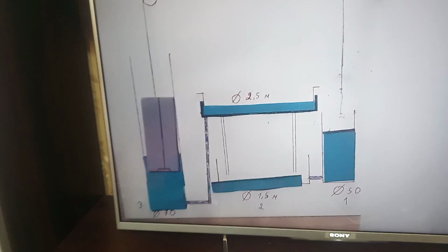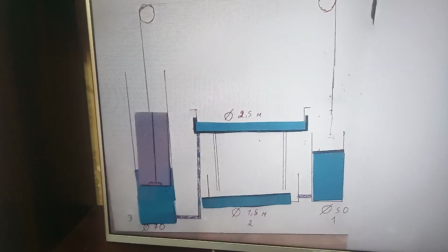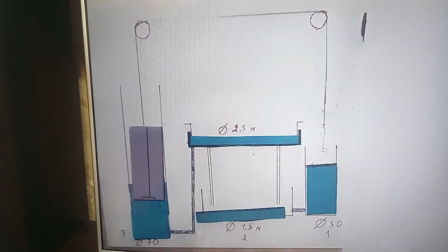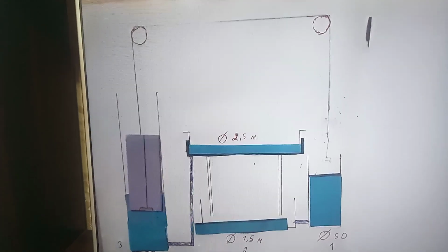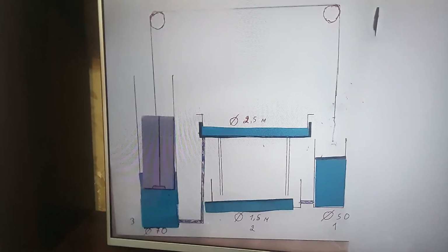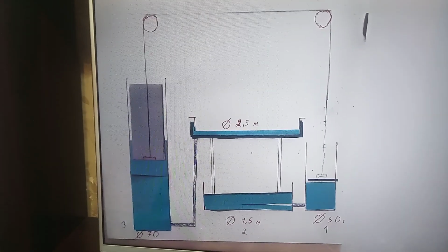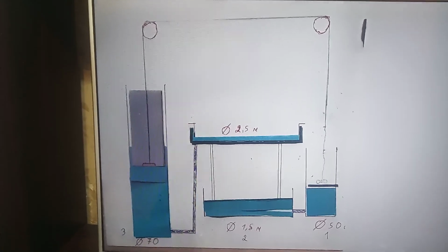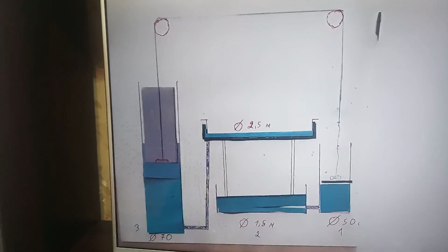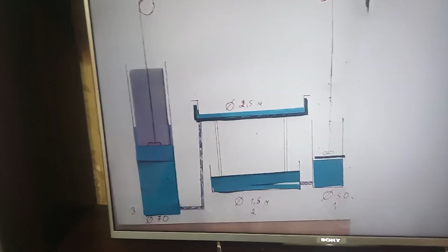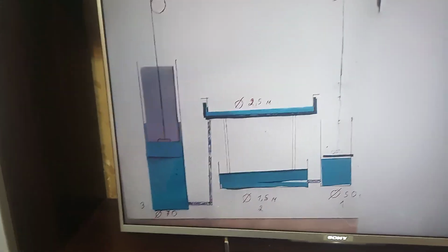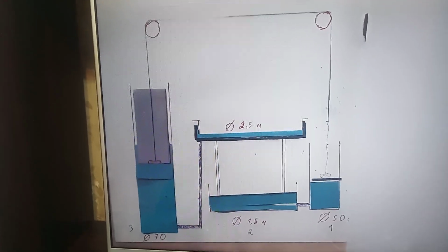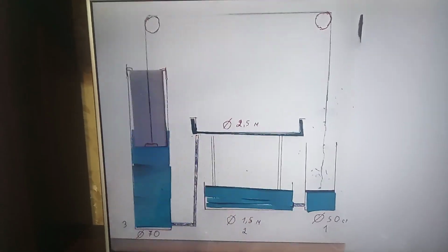After the liquid flows out, the weight of the piston with the reservoir will decrease from 900 kilograms to 361 kilograms, which will allow the piston of the first cylinder to maintain an advantage in pressure on the liquid, and the liquid from the reservoir, moving into the third cylinder, will lift the float by 1 meter and 40 centimeters, which will allow the cable to catch up with the piston of the first cylinder and engage with it, and